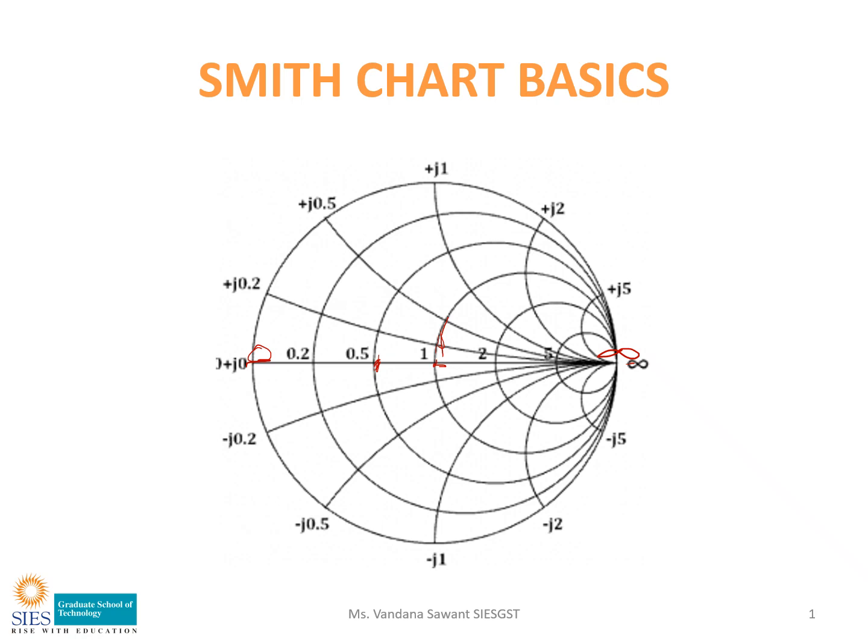Similarly, you can observe some vertical circles also running from the top to the center line on the Smith chart. These vertical circles are called reactance circles, or jX circles. Positive jX values are represented in the upper half of the Smith chart.